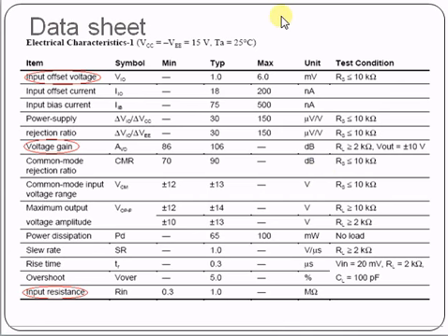Data sheets are important because they provide realistic data of the device, instead of the ideal model of op-amp that we've learned. It shows you the limitation of the device and helps you to determine whether to use the IC or not. For example, we often idealize the input resistance to be infinity. But according to the data sheet, you know that the Rin is typically 1 megaohm. The value will affect the approximation of the ideal model under certain circuit configuration.